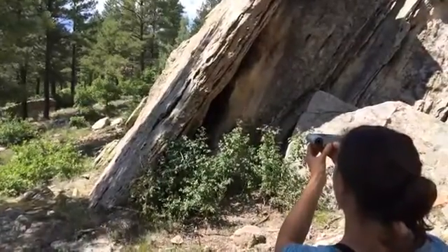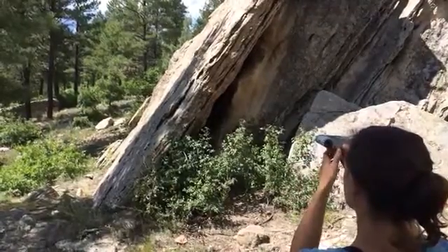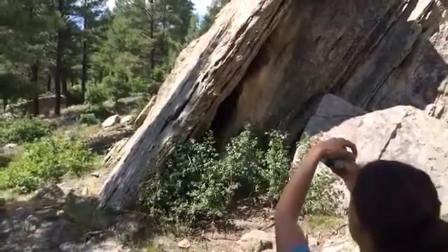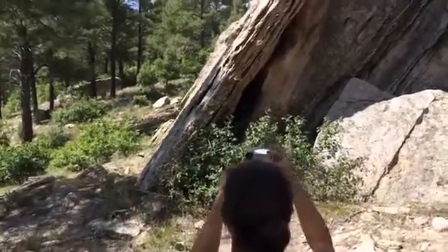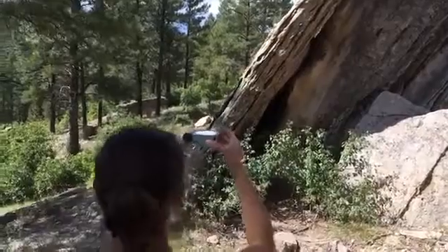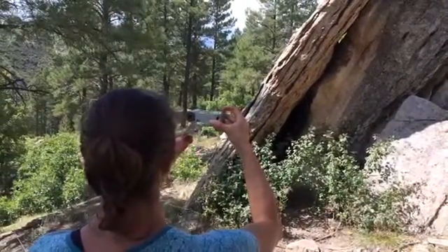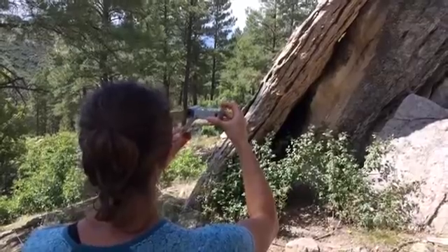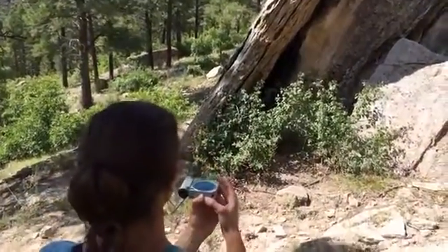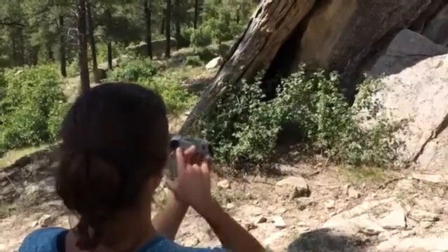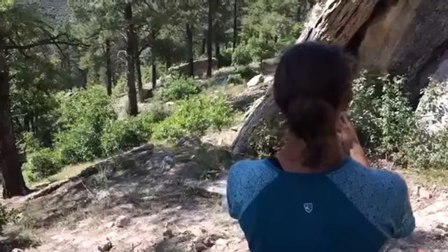Now with the axis at eye height, you can sight your measurement plane through the sighting tube, rotate the lid and align it with the plane being measured, level the compass face using the side vial level, and press and release the needle button 3 times to reset the magnetic needle. Then you can move the compass away from your face to take note of strike, dip angle, and dip direction, which in this case is off to my left.